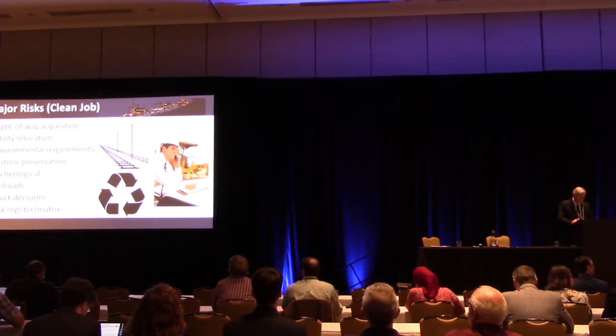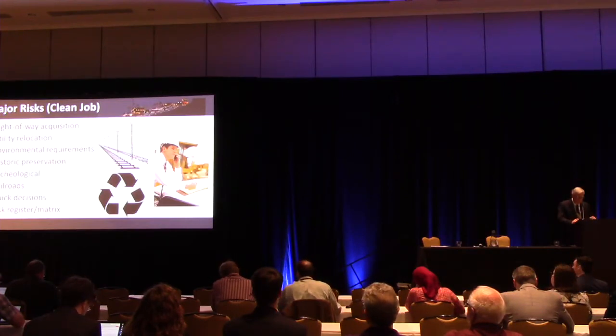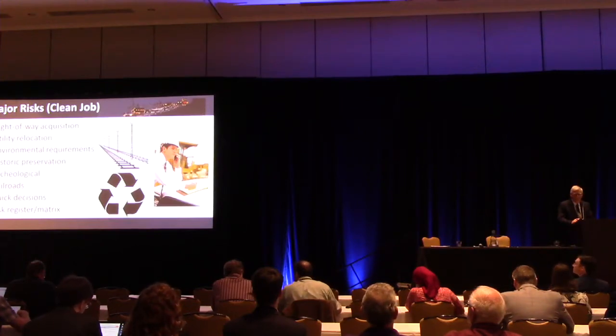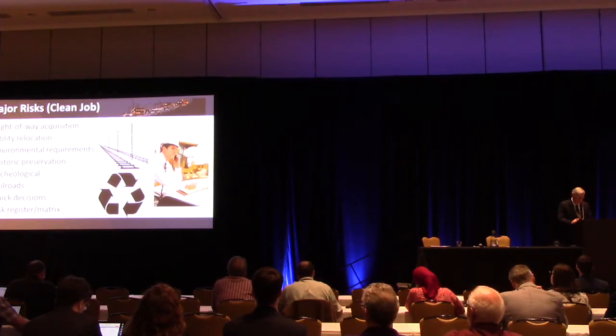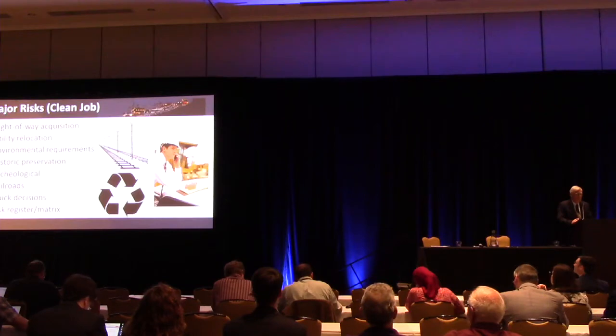Again, contractors want clean jobs. Right-of-way acquisition is complete, utility relocation is complete, environmental requirements have all been taken care of, historic preservation issues have been resolved. Archaeological sites are sometimes surprises, as we all know, and you're trying to avoid those. Railroads came up in every meeting we had. Evidently there's something about railroads that just doesn't cooperate very well with us building highways, and that is true all over the country. They also want somebody at the job site who can make a decision quickly.